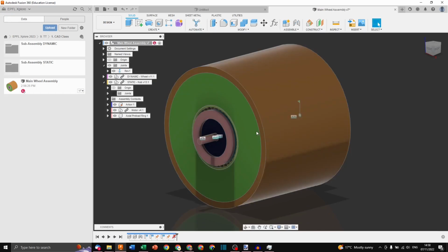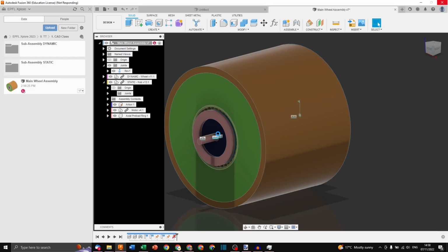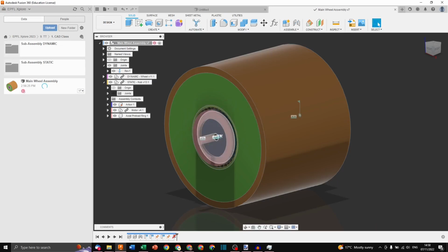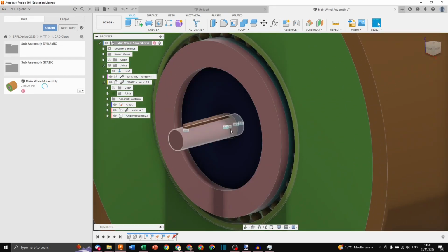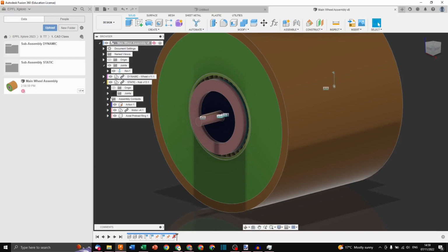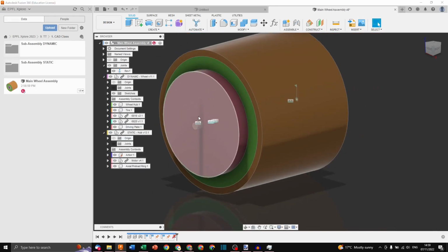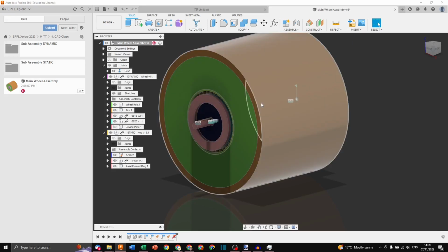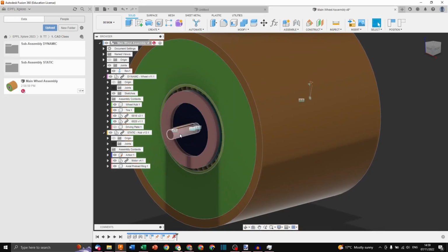So the caveat in the design is that, well, the motor arbor doesn't rotate, when in reality, the arbor of the motor here will of course rotate. That's the point of the motor. But if we do this, once again, it's complicated because you need to split the motor shaft between the motor body and have the keyway be rotating with this driving plate that's right here and hidden. So we make it simpler in CAD. The whole wheel rotates with the bearing and not the motor shaft. So it's false, but it's easier for Fusion and it works perfectly fine. And if you're going to do videos to sell to a sponsor how your design works, they will not see any difference. They won't notice it.